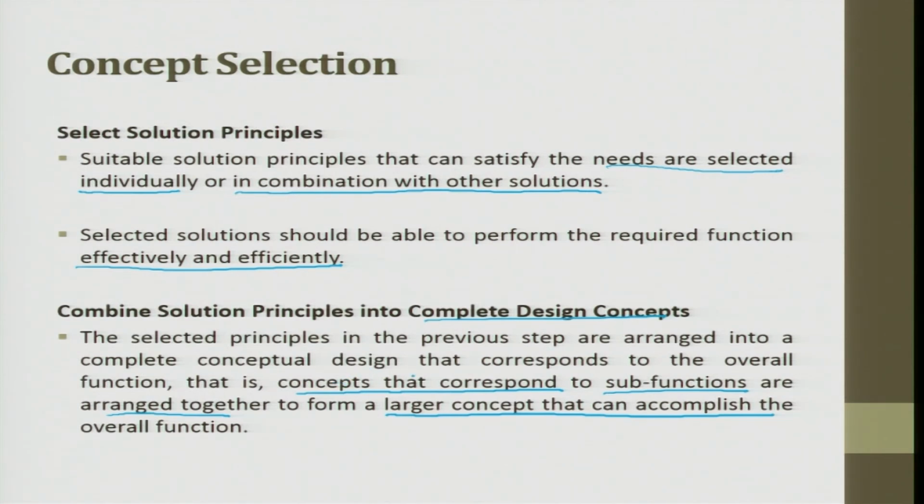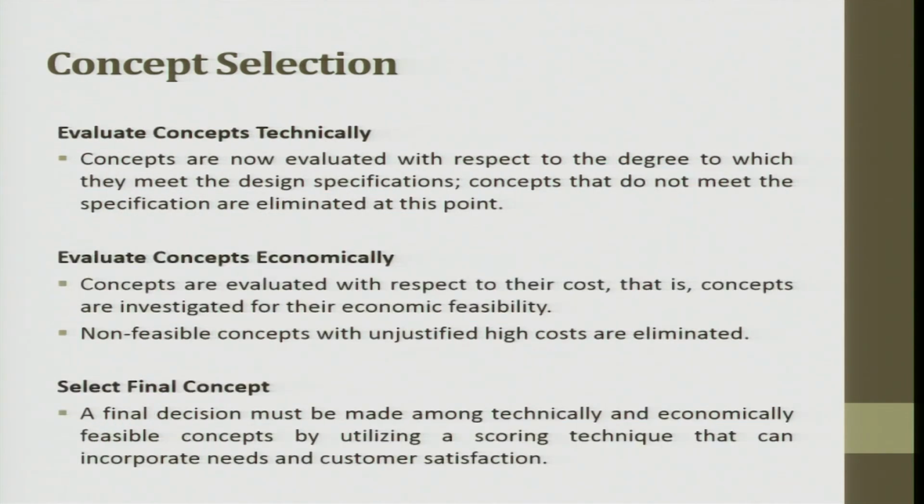The selected principles that correspond to the overall function, that is concepts that correspond to the sub functions, are arranged together to form a large concept that can accomplish the overall solution. Evaluation, concept technical: concepts are now evaluated with respect to the degree to which they meet the designer specification. The concepts that do not meet are eliminated. With keeping economics, concepts are evaluated with respect to their cost, that is concepts are investigated for their economic feasibility. Non-feasible, we drop it here.